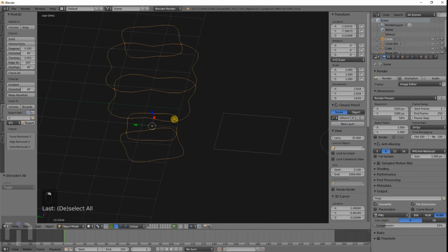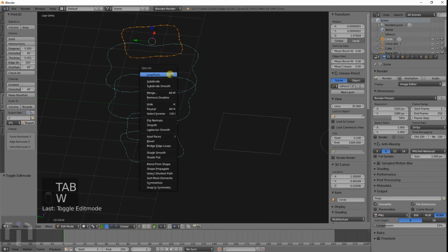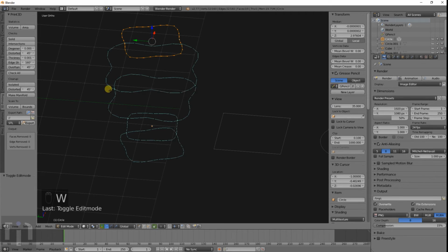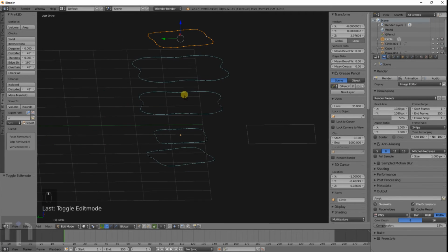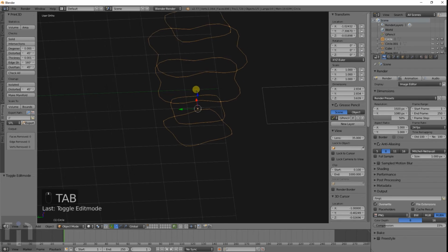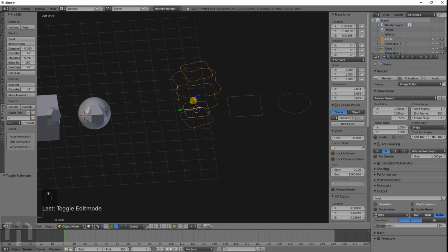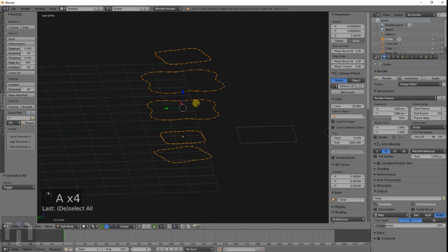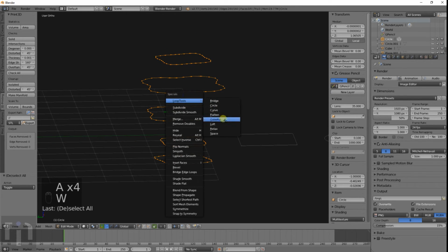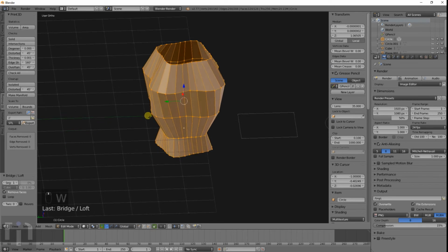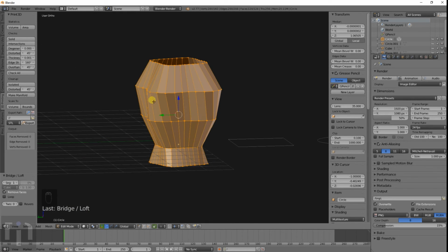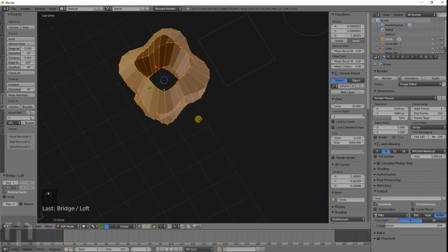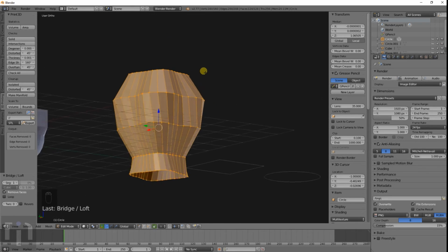That's the G stretch. The next tool, which is kind of unique, it's pretty cool. Here I started out with a circle and I just made them different sizes. And the next tool is the Loft. What it does is it joins all the different loops that you have and creates a shell of an object of that.